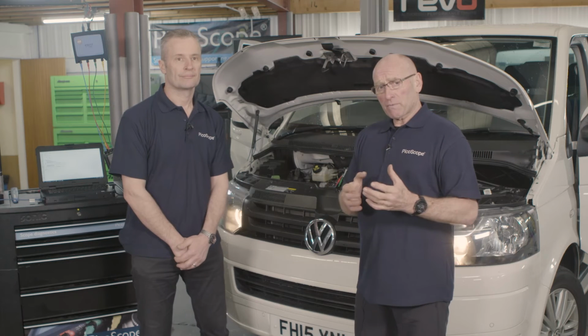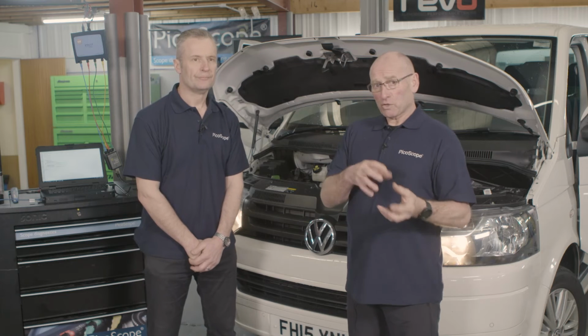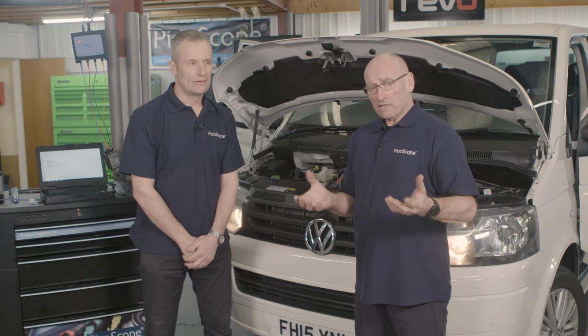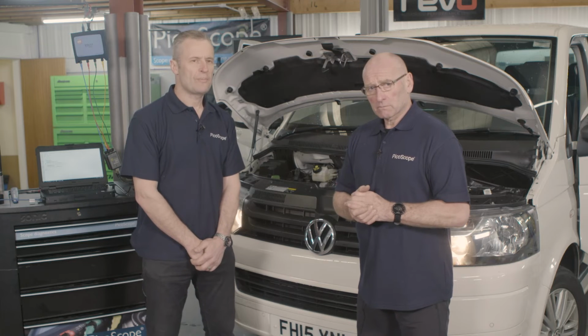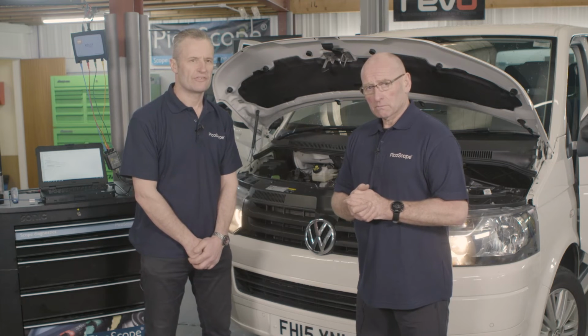And I guess from this setup, would you also recommend moving the position of the microphone once you're honing in on the noise to perhaps increase the amplitude of the results? Yeah, the opportunities are endless really, because certainly always keep a microphone in the cabin as a reference, because that's what the customer can hear. Perhaps keep one in the cabin, one in the engine bay, and also keep the accelerometer as well, so you've got 3 points of reference really.